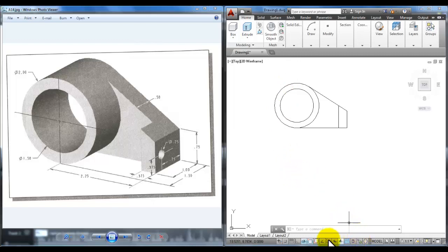And then at the bottom left corner of your screen, you'll notice that there are a lot of status bar commands that we've been learning. The ones that you can use as an option would be the fifth one, which is polar tracking, and the sixth one, object snap. Those two can be the minimum ones that you use, although some of you have ventured into working with other tools in this toolbar.